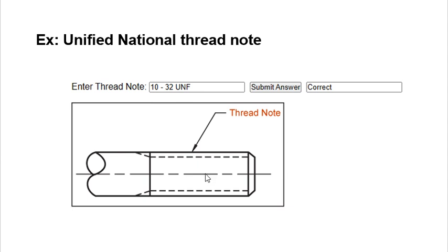When you take a look at it, in the question it is number 10. Find the thread that you've got to write, the thread note. Since it is 10, we're going to write down the diameter is 10. When you write in 10, or 12, or 11, or 8, and you see the number sign, a little pound sign right there, you know that is your diameter.